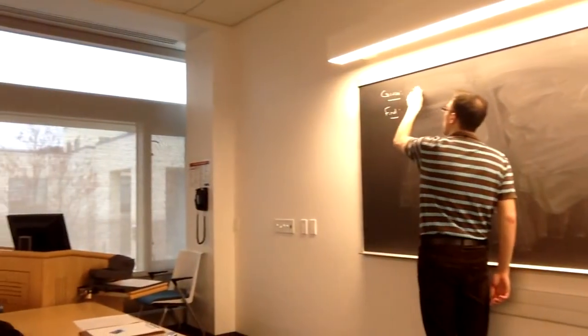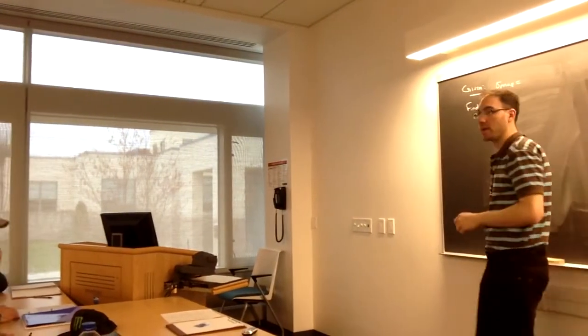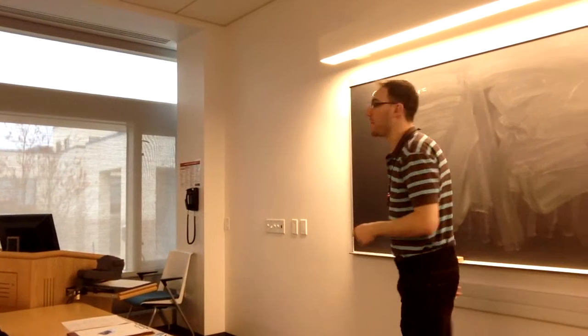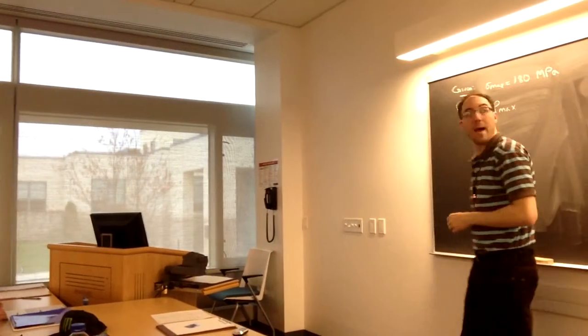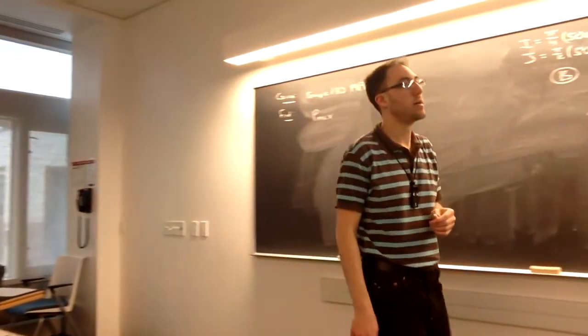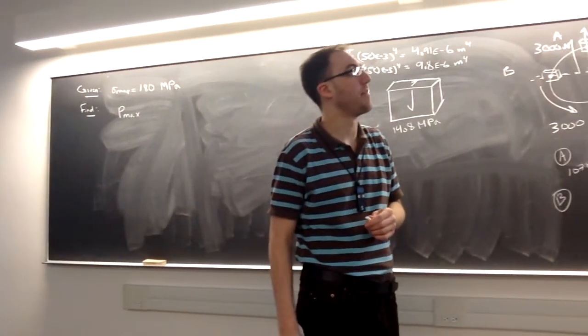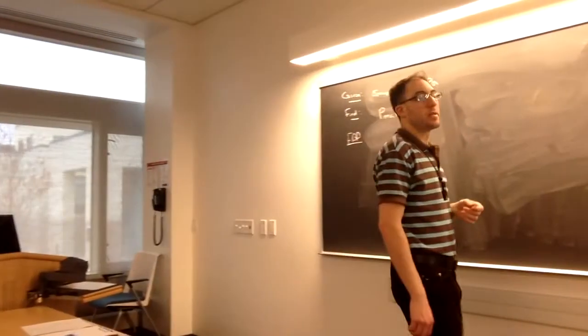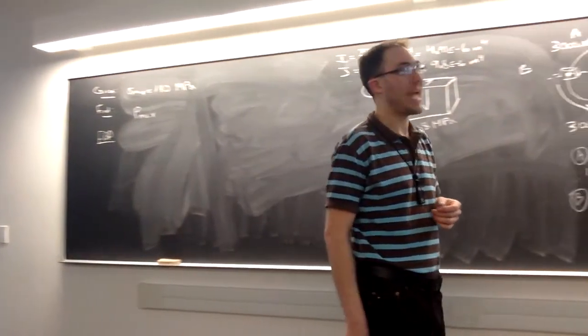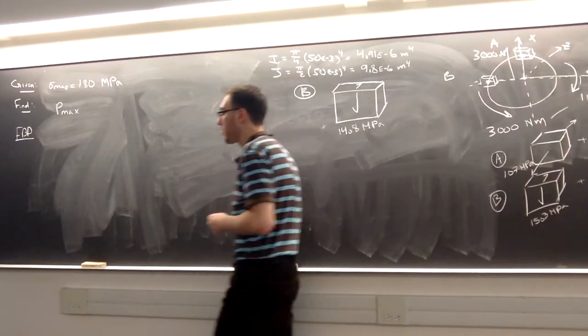We're told the maximum normal stress we can have anywhere in that cross section is 180 megapascals. We want to find the maximum force P that we can apply before we're going to have failure in our material.